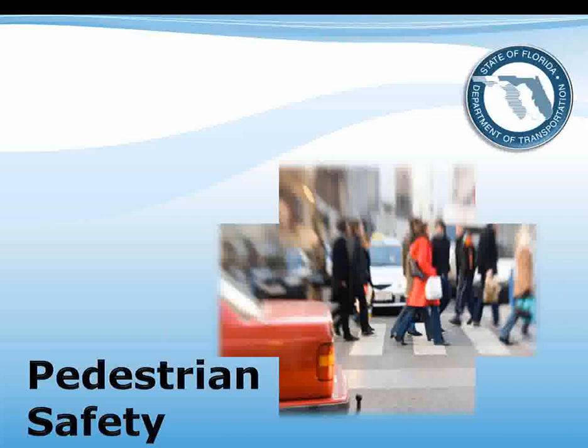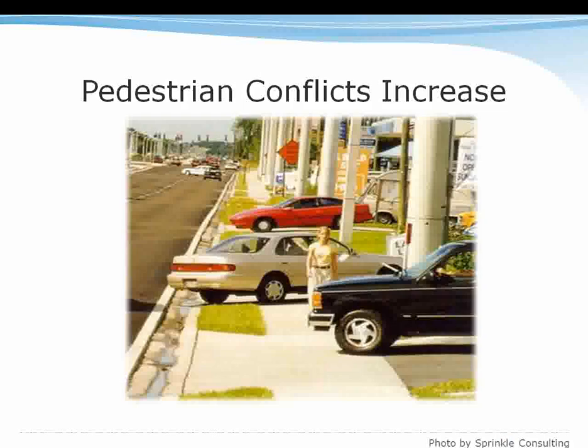But it's not just the automobile safety that we're interested in. We are also interested in the pedestrian. The pedestrian is the most vulnerable of all of our roadway users, and good access management is one of the best ways to help the pedestrian. Each driveway increases pedestrian conflict.